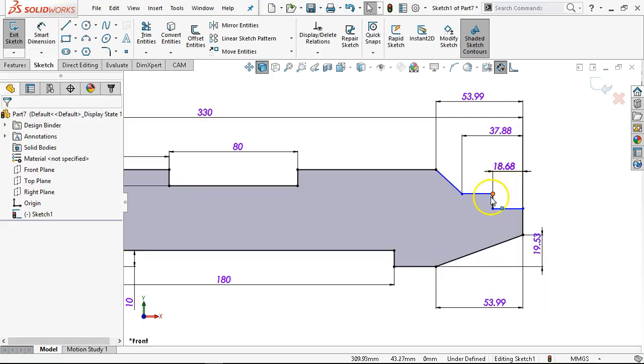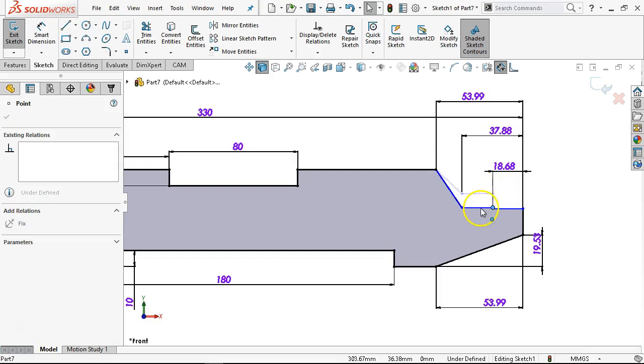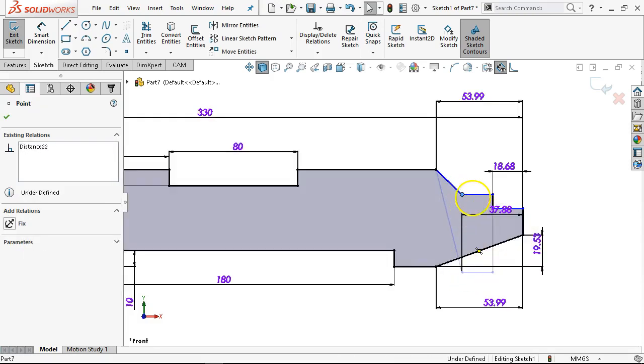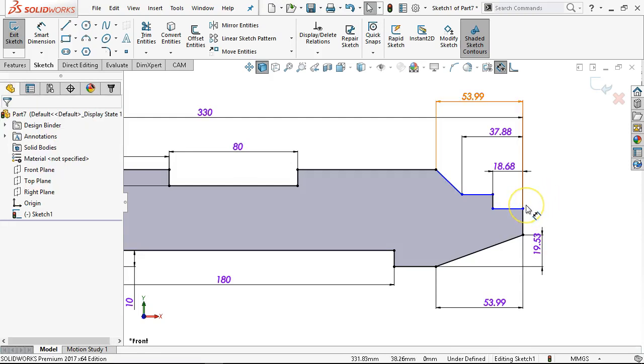Well, let's just see what happens when we go to move. All right, so the angle's changing, we get inversion, the shading goes away. As soon as I go from a single enclosed region to multiple regions, so 1, 2, 3, then the shading drops off. So you have this instant visual clue that we're overlapping or we have an opening somewhere.